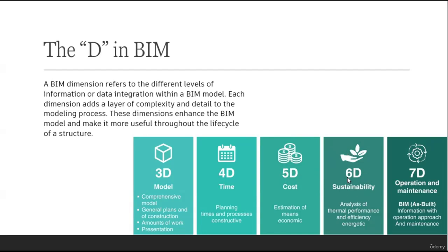Okay. The 6D involves the sustainability part. Sustainability concept is rather dependent on the energy analysis study. In sustainability or the 6D analysis, the thermal performance of the materials that are used in the model are analyzed. We can compare the performance for different materials based on their application in the model as well as their actual